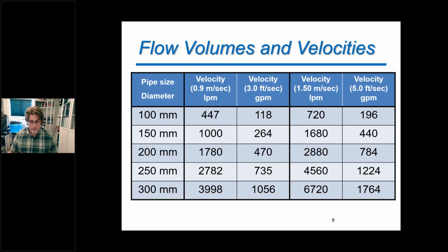If you are just going, let's say, out of a 2-inch blow off on the end of a line, and you are not able to reach these velocities, these flows, then that's going back to your plan. Okay, I've got this long 6-inch main. I went to the very end of it. All I've got at the end there is a 2-inch blow off. I measured the flow out of it. I only get 300 gallons per minute out of here. So I'm not achieving that 5 feet per second. I'm not achieving optimum. Then that might be something, okay, I need to go back to the plan. I need to maybe put a plan together to put in a hydrant down here where I can get more flow, because I can go out of both ears of the hydrant instead of the blow off, whatever it happens to be as part of your plan.